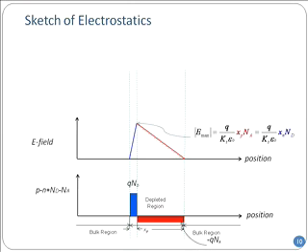But the maximum electric field, how will you calculate that? Well, you will calculate it as the area under the blue curve. How much is that? You will have ND multiplied by Xn, right? That's the area under the curve, distance multiplied by height, and you have to divide by this epsilon so that you get the electric field. That's the charge and you will get the electric field.